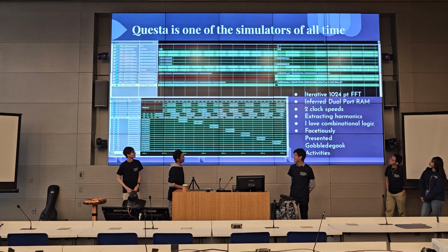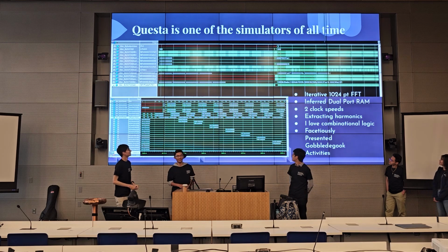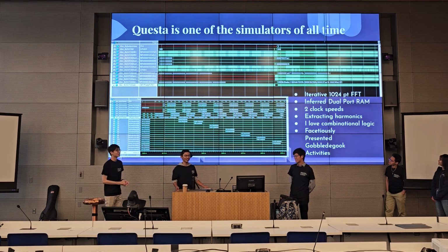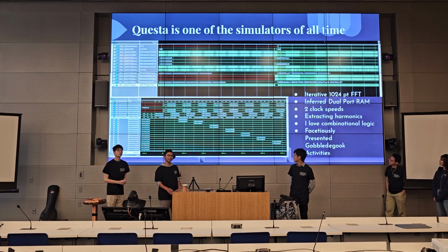Oh yeah, so for our project, we needed to make a 1024 point FFT, which is far beyond the size that staff teaches us. The reason for this is that then the bin width is about 4 hertz, which we experimentally determined is good enough for capturing the peak.